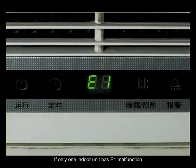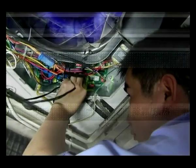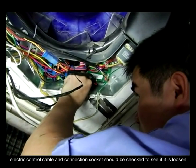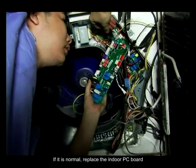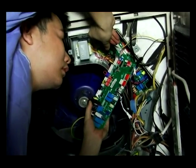If only one indoor unit has E1 malfunction, electric control cable and connection socket should be checked to see if it is loosened. If it is normal, replace the indoor PC board.